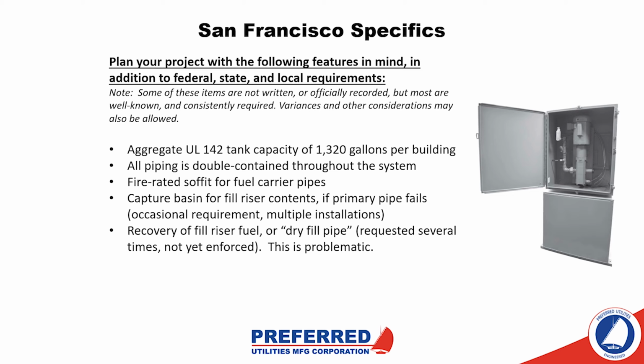We can terminate the pipe secondary in the basement or wherever the fill port is, and wherever the low point in the piping is, that is to say, and basically calculate the size according to the contents of the fill riser pipe. It's not a situation where they're concerned about the tank siphoning out. It's just the contents of the fill riser pipe. So we have dealt with that several times.